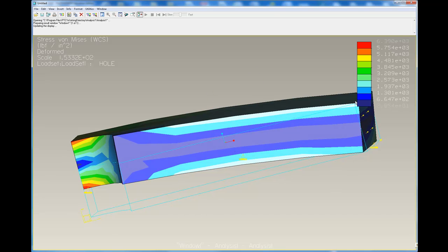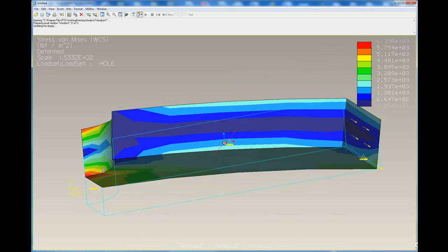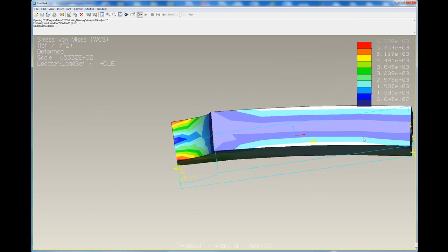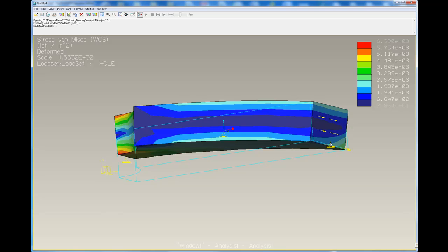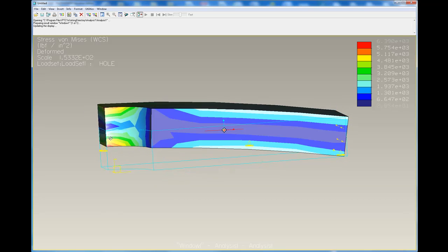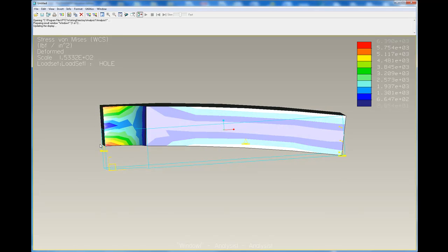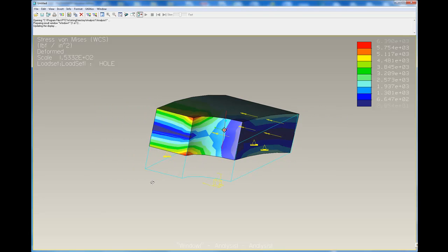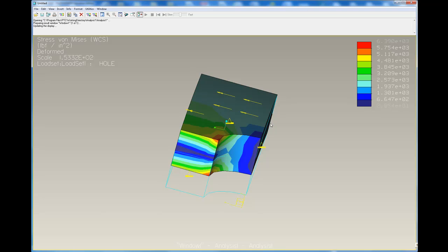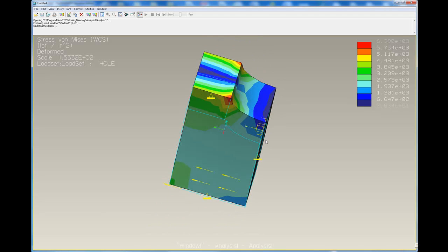And what's happened is, by creating this bending moment on this surface, because of the loading, it's caused this surface to tilt, as it should. This surface may no longer be planar, I don't know. But it caused this surface to move upward, but this surface remained both planar and did not travel in this x direction. Okay? And this surface should have remained perfectly straight and perfectly flat on this surface right here, and it did.